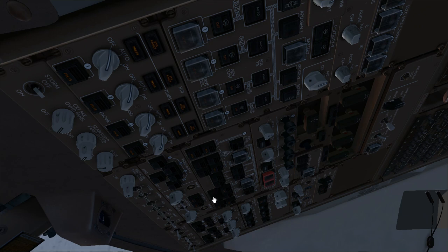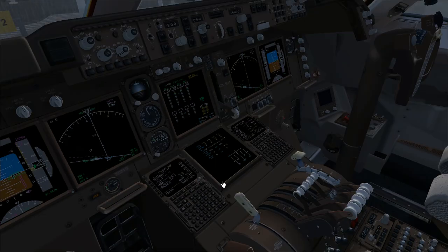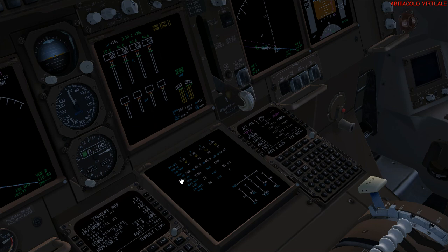Anyway, tank 3 is actually cross-fed to the second to maintain the balance between the two. If we go to the start page now, you will see the APU starting up. We have the APU line here with exhaust gas temperature, N1 and APU oil quantity. When the N1 goes over 95, you will see the APU running message, as you heard. And we have now full N1. The EGT is stabilizing, so we are just finishing starting up the APU,